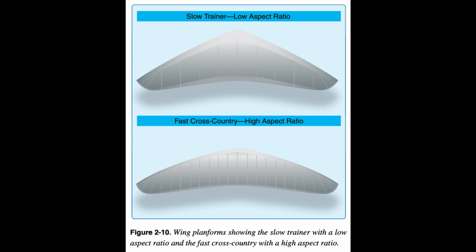If flying the same wing with 1 person and a lighter total weight of 500 pounds, the wing loading would be 2.5 pounds per square foot. In the small, high-performance wing of 140 square feet loaded at 1,000 pounds, wing loading would be 7.1 pounds per square foot. Gliding flight is flying in a descent with the engine at idle or shut off. For example, use a glide ratio of 5, which is 5 feet traveled horizontally for every foot descended vertically. Glide ratios vary significantly between models.